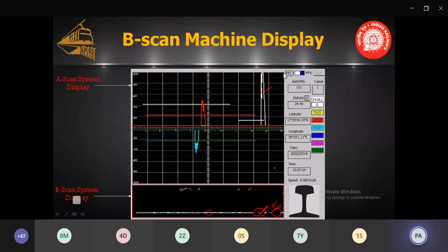Now if we select this region, we will be able to get a larger image. Suppose this is covering a 5 kilometer range, and if you are selecting, this may be about half a kilometer or 500 meter length, and accordingly you will be able to find out what is the correct length where the problem is there. So you can identify, okay, this much length there is a problem with the back wall echo. So we can find out the reason why it is there, is there any lack of contact, or some other problem, or we can repeat it.